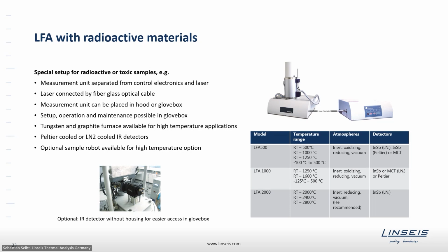One can go using liquid nitrogen, and a special series is the LFA 2000, for high temperature applications above 2000 degrees Celsius, which also uses the laser. All of these models can be used within different atmospheres. Mainly, laser flash measurements are done in vacuum or, for example, in inert atmospheres. These are the most used atmospheres.